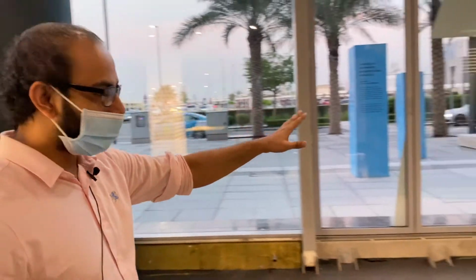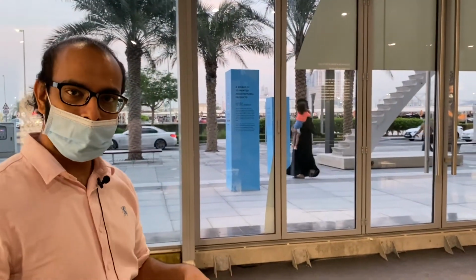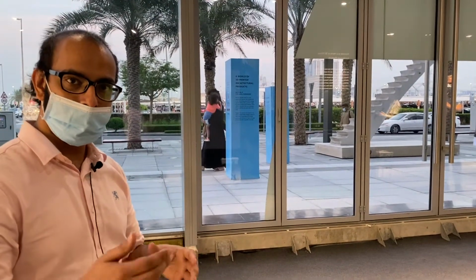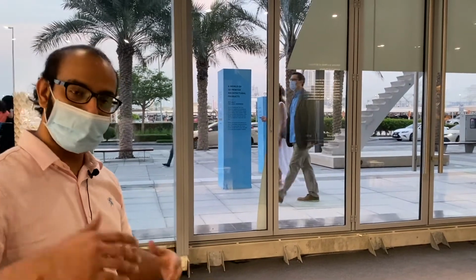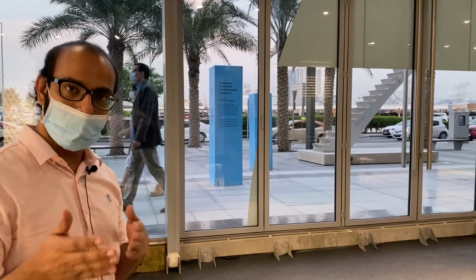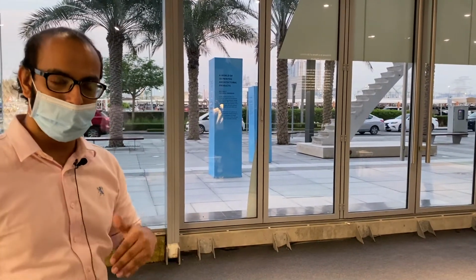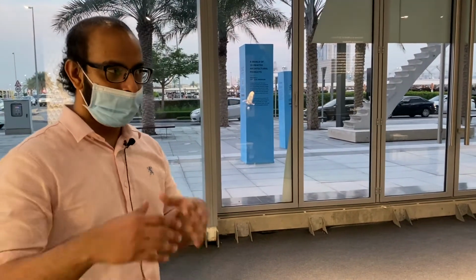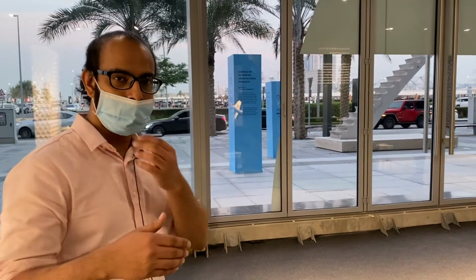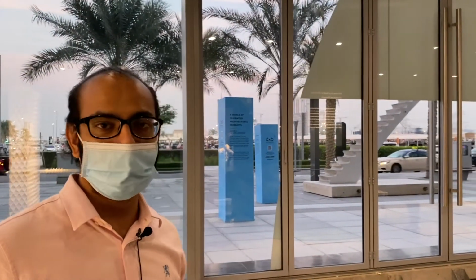And if you look outside, we have the stairs. And the stairs, how we do it is we 3D print the formwork, and then we pour the concrete onto it, and we also have reinforcement. So we can absolutely print anything to any scale in one piece or any kind of form. So facade, if we have projection or parametric form, which is usually tough to manufacture using conventional techniques, we can make a formwork using 3D printing technology, and just pour the concrete to have the architectural facade.